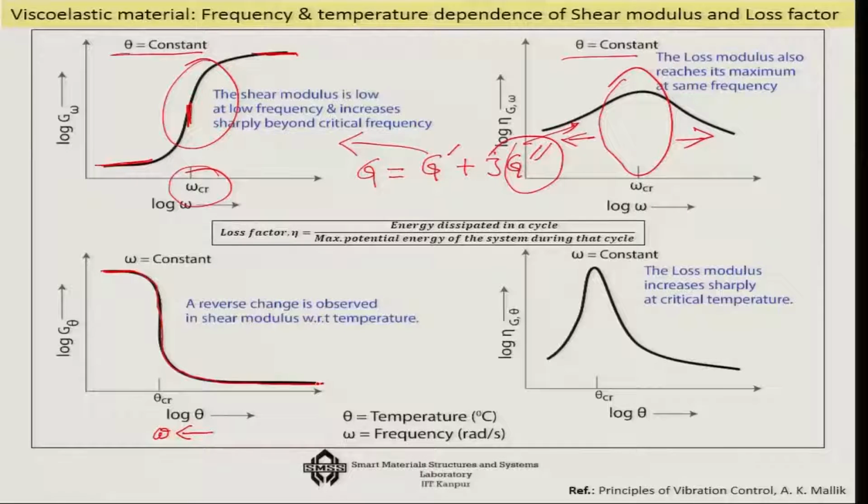In terms of the loss factor or the damping, at low temperature once again the damping is not very high, but beyond a particular temperature the glass transition happens, and the chain mobilization occurs. So, you get a good loss factor here, and after that temperature the loss factor drops down again. So, this property we have to keep in mind in terms of modifying the system parameter.